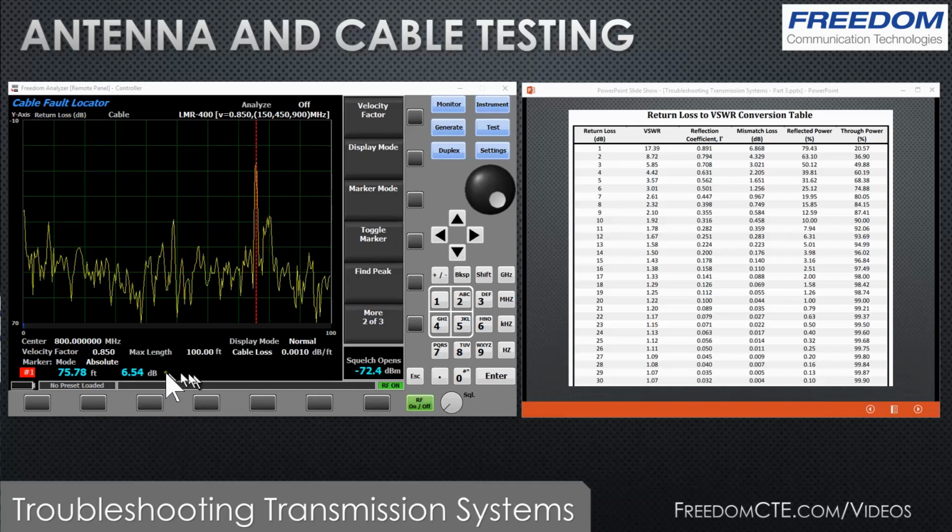Here's the result. Again, I've created an open circuit, and you'll recall the last time we did that with the cable loss compensation, we ended up just under 1 dB. You'll notice here now that we're looking at 6.5 dB. How do we know if that's anywhere close to correct? Well, let's take this length.